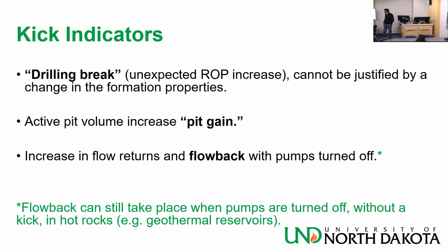Now, flow back, what is flow back? In general, it's something flowing back, when your fluid comes back to the surface. Okay, but on the rig, I have two indicators, mud in and mud out. If they are all equal, then it means it's good. But if I turned my pumps off, and the mud out is higher, that's the flow back. So how would that look on my indicators? The mud out is going to be higher.